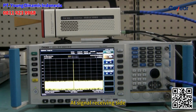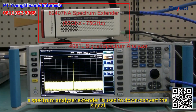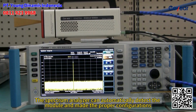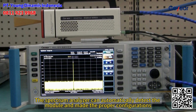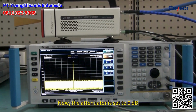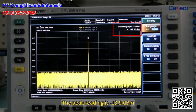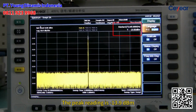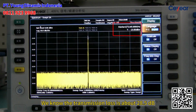At the signal receiving side, a spectrum analyzer extender is used to down-convert the signal. The spectrum analyzer can automatically detect the module and make the proper configurations. Now, the attenuator is set to 0 dB. The peak reading is minus 13.9 dBm. We know the transmission loss is about 28.5 dB.